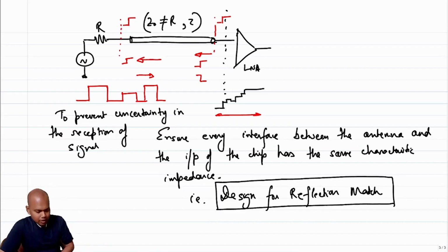Okay, and this is a problem that you are not going to see in typical analog circuits. There are two reasons behind that. One is typical analog circuits work at much lower frequency than gigahertz and multi gigahertz. They typically are, as of today, sub gigahertz, a few hundreds of megahertz at max, right? But more importantly, even if they work at multi gigahertz, the entire analog circuit sits inside the chip, right? Because they sit inside the chip, the dimensions are much smaller than the wavelength.